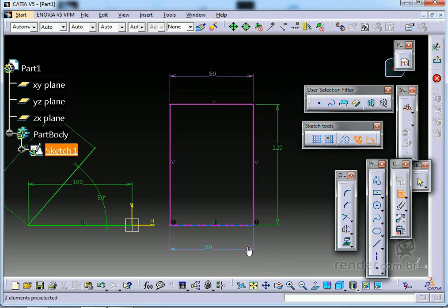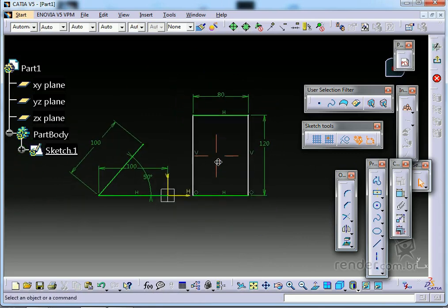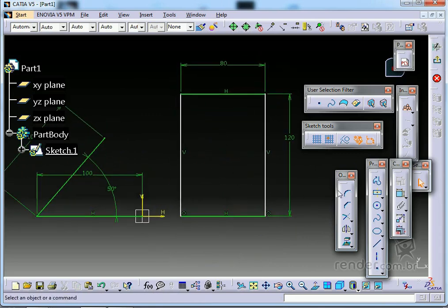When I remove this one here, I'm going to select it with the left button, because it doesn't erase, because I have to give 2 ESCs to get out of this fixed command. 1, 2 and it went out. I click on it, hit L and it's already green once again. This is our sketch option for working with lines.